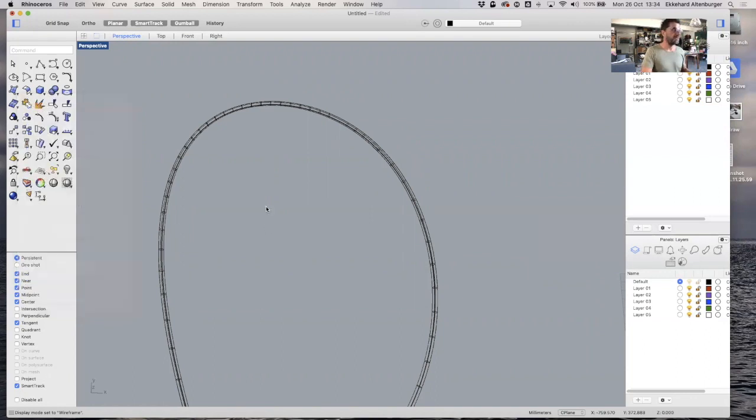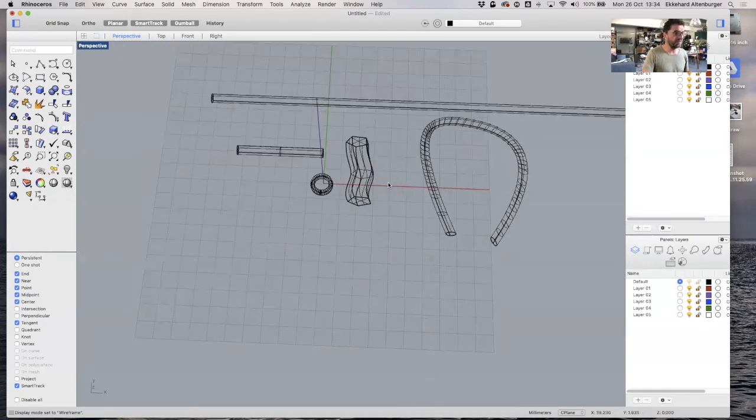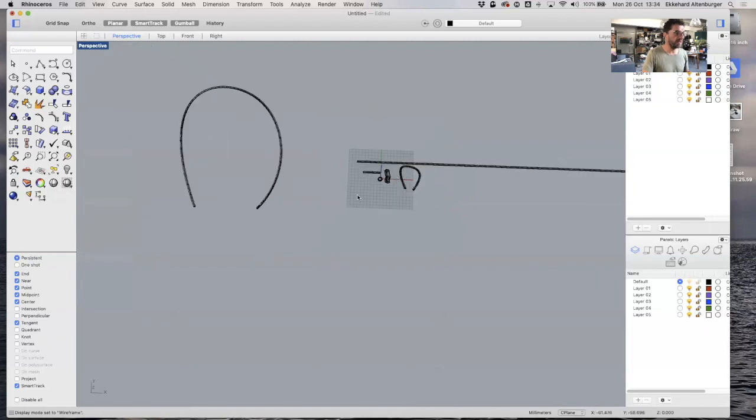So best is really to just practice for 5 minutes all the options and figure out how it works with straight lines. You need to be aware how to get your diameter of the ring to a right angle to the rail you want to sweep. But it's quite easy to create these sort of free forms with this method.